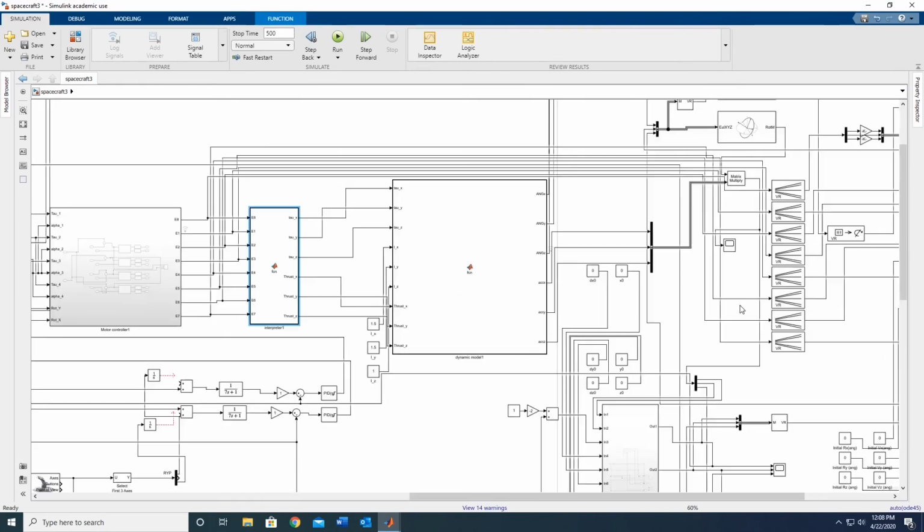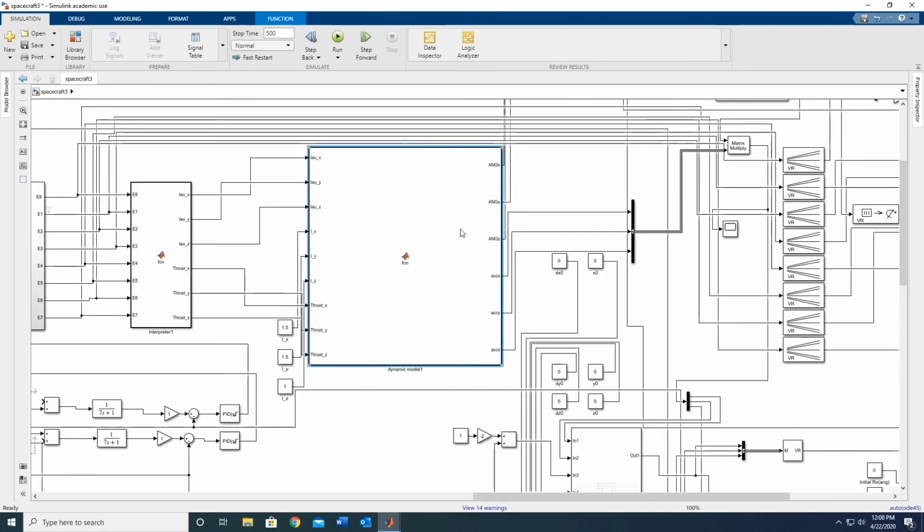Okay, so then what this block does is it uses some physics to convert using the dynamics of my model, so some moments of inertia, and then some predefined mass terms. It computes my angular accelerations in x, y, and z relative to the vehicle. And by the way, these values are not slave to the axes.